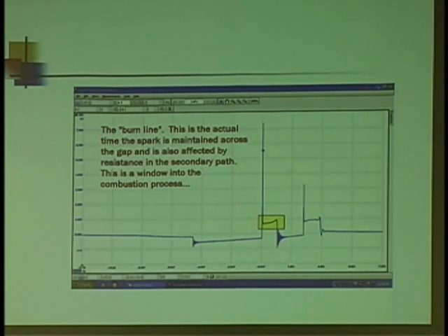And because there's going to be plenty of fuel left over by the time the coil is exhausted, it's going to stay fairly flat or even start sloping downward as the resistance decreases. Conversely, if it's lean, it's going to take a little more spark kV to start it off, and I'm going to very quickly run out of fuel in the gap. And what happens then? The resistance increases, so I'm going to see it sloping upward.